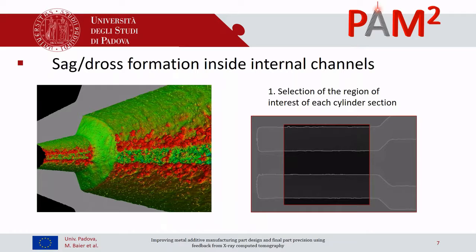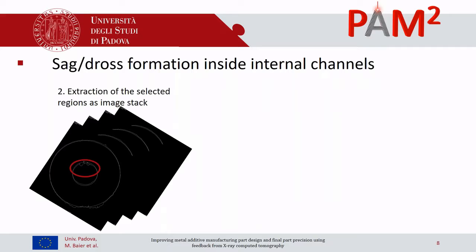defect in particular. So what we've done then was basically aligning our channels in one section perpendicular to the channel direction, and extracting stacked images of 780 projections in a spacing of our voxel resolution, which was in this case 10 micrometer.